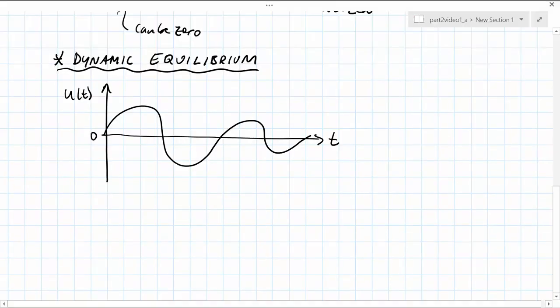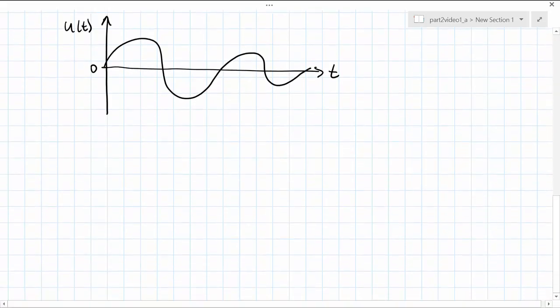The objective of a dynamic analysis is to determine the time-varying displacements of our system. An example of such a response is shown here, where we plot time on the x-axis and the displacements as a function of time on the y-axis. To achieve this result, we need to construct an equation of motion which gives the behavior of our system. Typically, this is done by considering the resisting forces of the various components of our dynamic system.